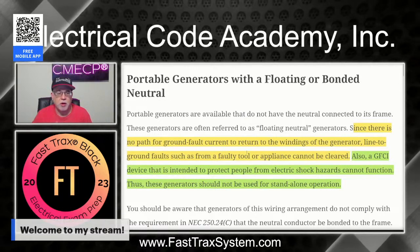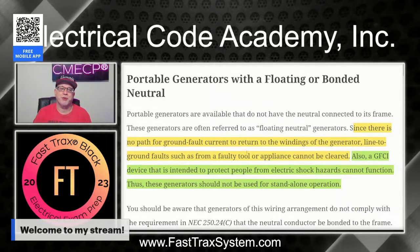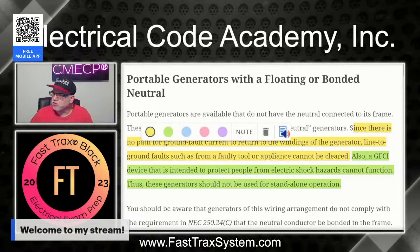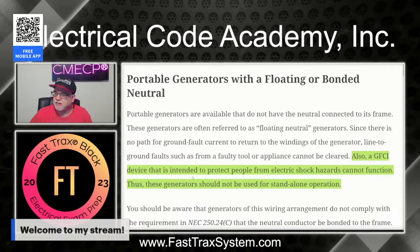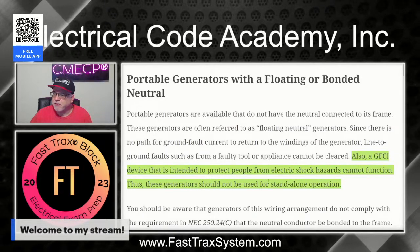If you're still using corded tools on job sites, it can create an unsafe condition if you're using a floating neutral type generator. Also, now we get to the green part. A GFCI device that is intended to protect people from electric shock hazard cannot function.